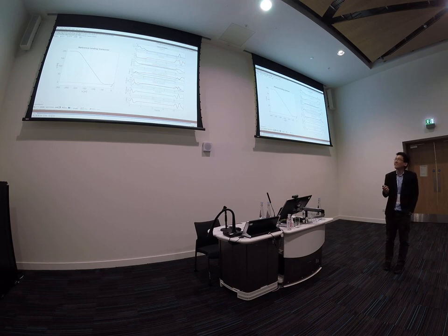The elevator is pushed up like this to pitch up the airplane. For pitch up, you have to see the theta angle. Theta is increased here. And then the plane falls into the stall state. The vertical angle of attack is this line. The plane falls into the stall state here. The lift is increased because the elevator is deflected.